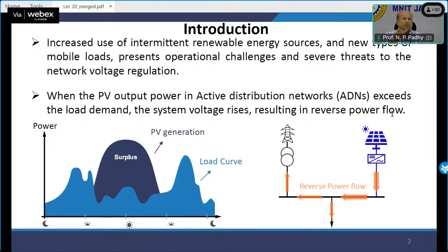Means if I compare these two diagrams, both technically and philosophically, you do have PV generation during a time when the customers are limited, and hence that energy is not being consumed, and hence it has to go somewhere else, or you have to derate, which is not ethical practice for renewable energy, or indirectly you have to put some load. So for the right hand side diagram, what I will do to avoid reverse flow, I have to put some additional load. What is that additional load? It is nothing but a storage device, any form of storage.